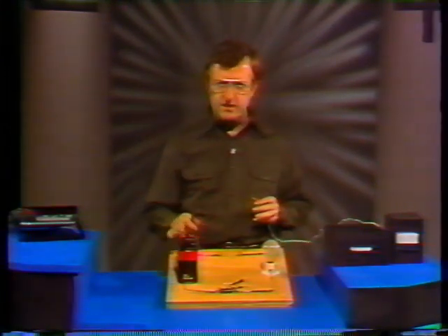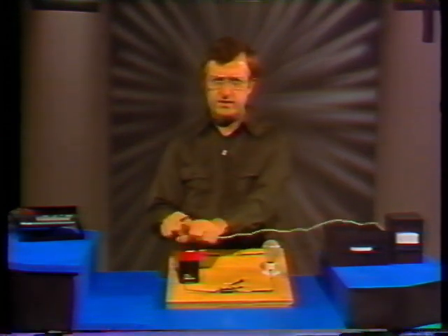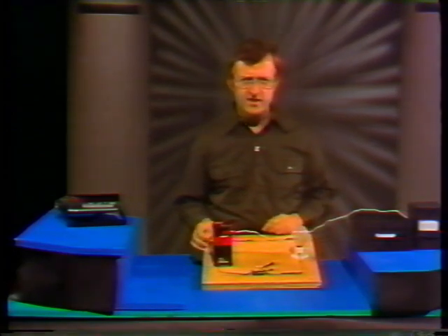Now, this is a 6-volt battery, so we should get a reading of about 6 volts. But it might be slightly less. The output of a battery varies depending on how old it is and how much use it gets. Now, we hook positive to positive, and negative to negative, and what do we get? This one reads about 5 volts. It's been used a lot, so that makes sense.